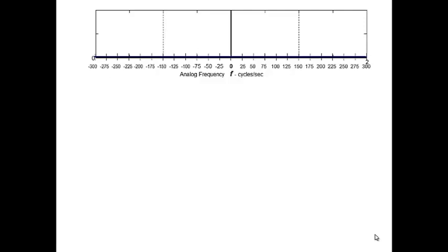And let's start off with a continuous time signal, xc of t, that has a magnitude of 4. We'll make it a sine instead of a cosine, 4 sine of 200 pi t. And we'll give it a little phase this time, minus pi over 3 for phase angle. And we want to know, if I sample that signal, F sample was, let's use 150 hertz, which is a ridiculously low sampling rate, for simplicity of the example.